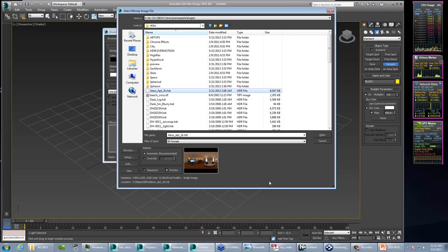And that mimics the way that the human eye works. Televisions automatically do a gamma value of 2.2, for instance. If you take a photograph with a digital camera, maybe adding a gamma of 1.8 to 2.2, depending on the camera, 1.8 is pretty typical. Well, 3D Studio Max needs to take that brightening out, and we had an additional option in here for the control, but they're trying to automate that more so that Max is smarter about how that works.